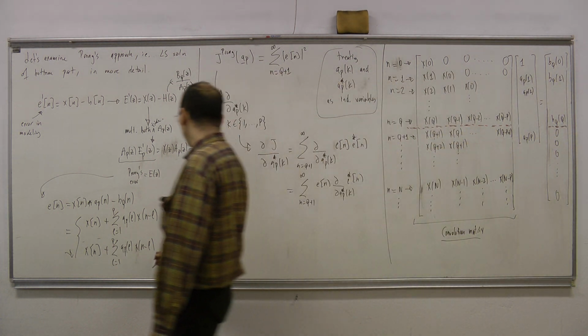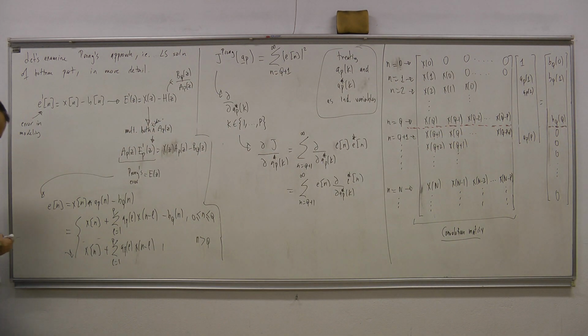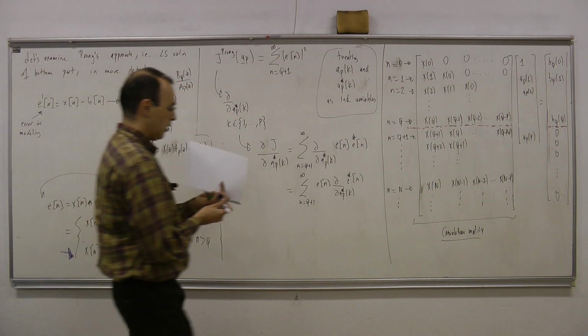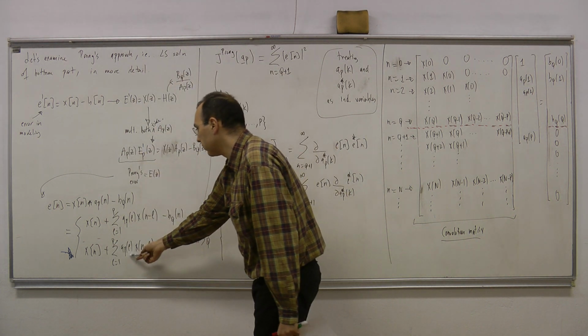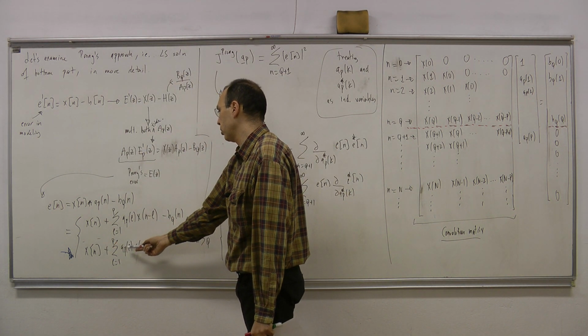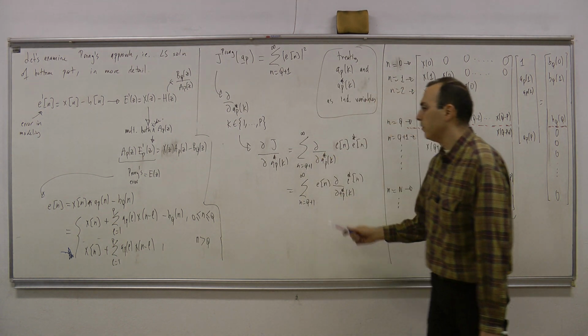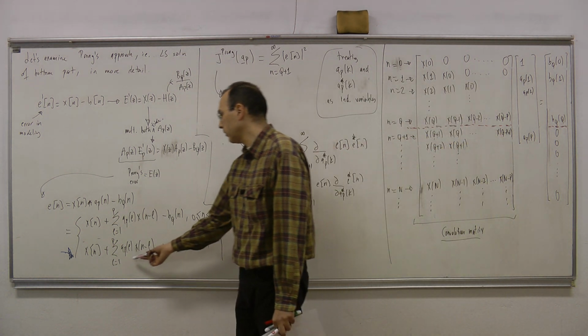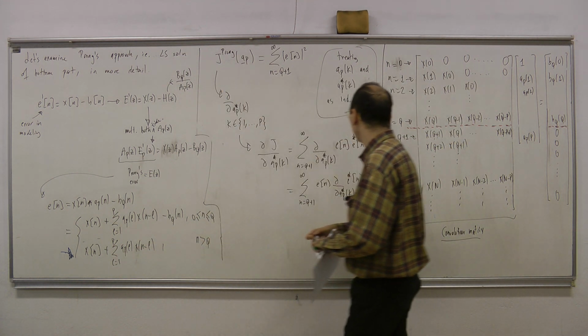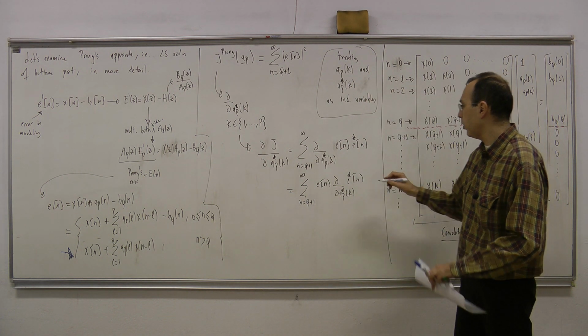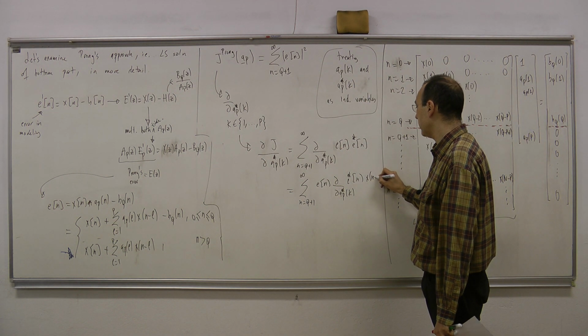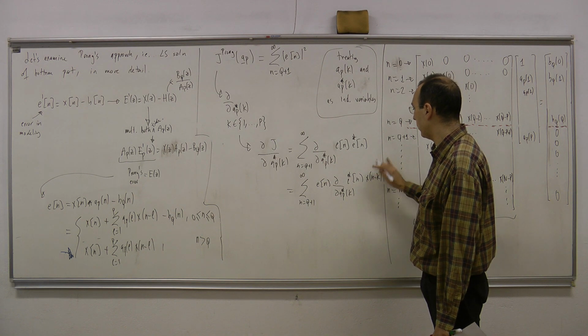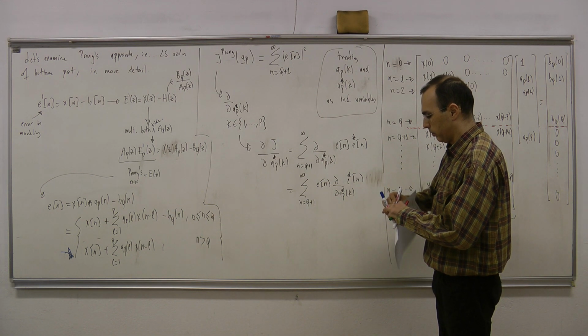Now take the conjugate of this error, this part. I'm talking about this bottom part. Okay, this part. So if you take its conjugate, okay, conjugates over here, and if you take the derivative with respect to a_p[k], okay, so what do you have? Well, you have x of n minus k, with a conjugate, sorry, not over here.